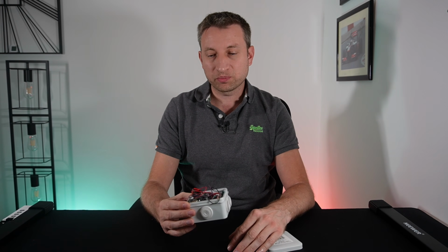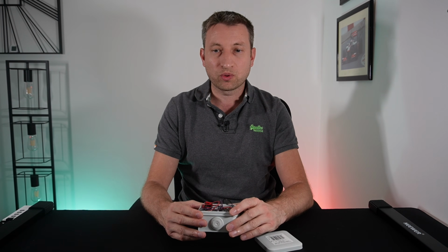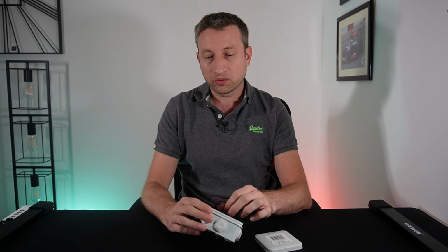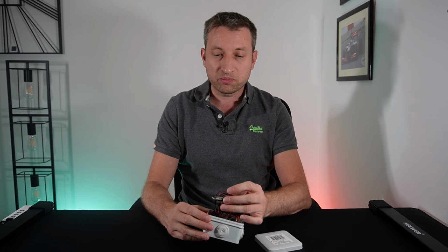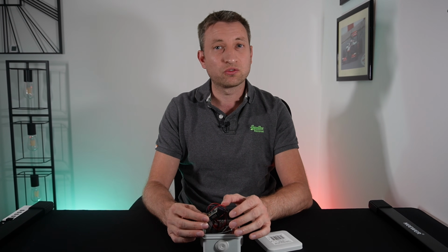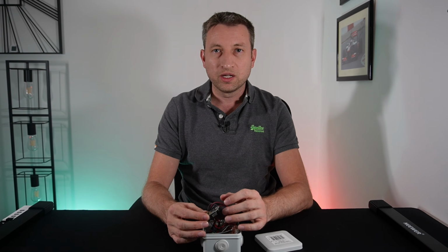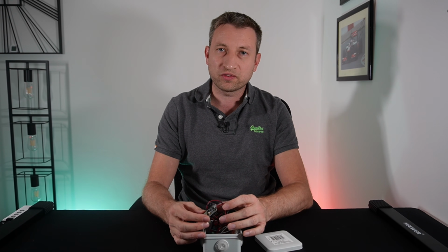Well, now we're going to say goodbye to the Arduino sketch and we're going to flash it with WLED instead. And WLED has made this really easy, thankfully. You simply go to a web page, plug this into a USB on your computer and then press install. If you've not done anything like this before, then you might need to install a driver, but there's a link for the driver on the website itself. And then once we've done that, we're going to go through the rest of the setup process. So to install WLED, we're going to need to get a USB cable and plug it into the computer and the ESP device.